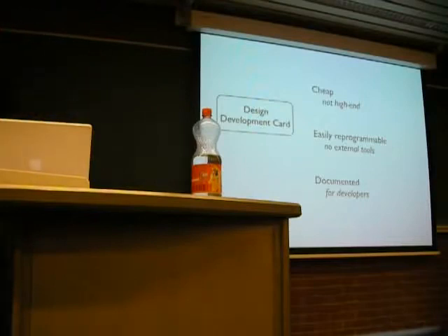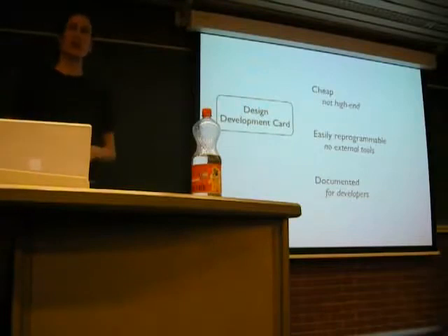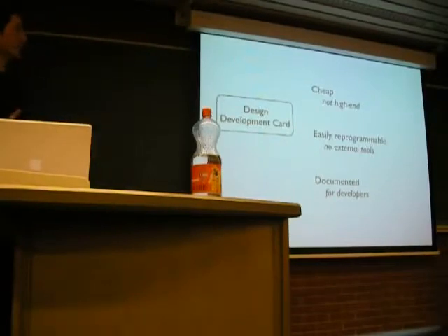So here, cheap, not high end, is really just to get smaller parts and get fewer features in there. Also because it was really focusing on graphics developers, not hardware developers, I wanted to make it easily reprogrammable. Usually, when you're talking about FPGAs and chips to reprogram, you're using a JTAG bus to communicate with all the chips. And for JTAG, you need a programming cable really, and these cables can run into the hundreds of euros if you really want just one cable, which is good.